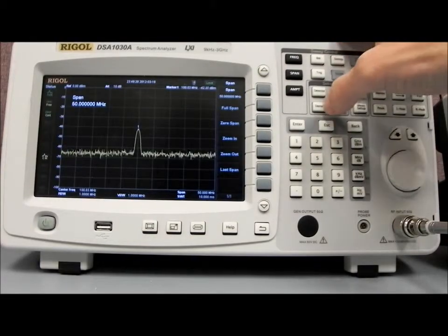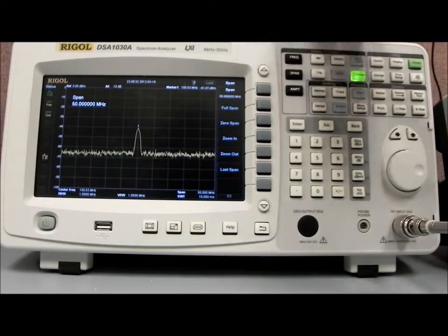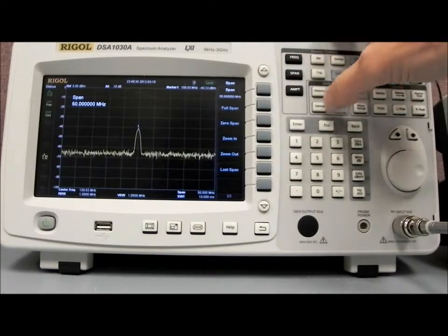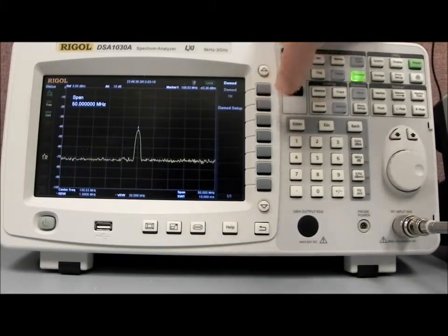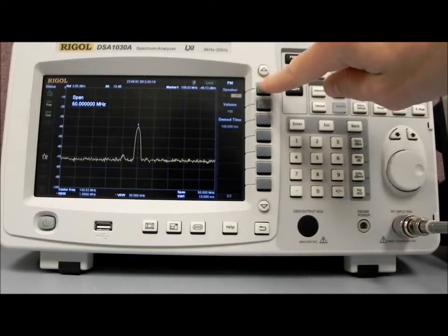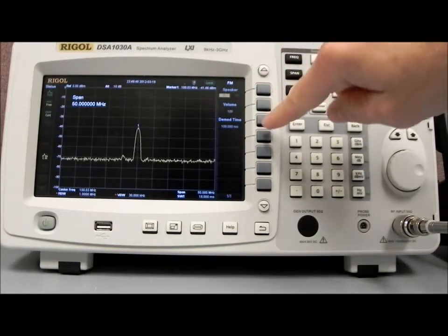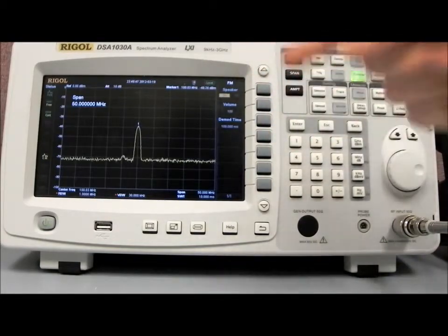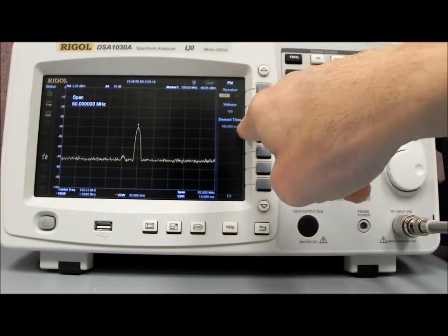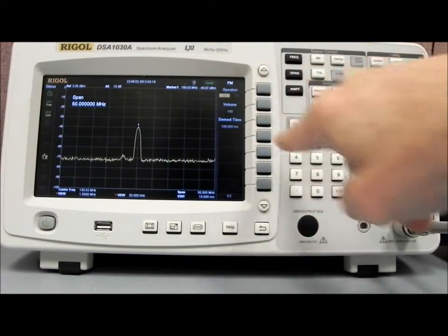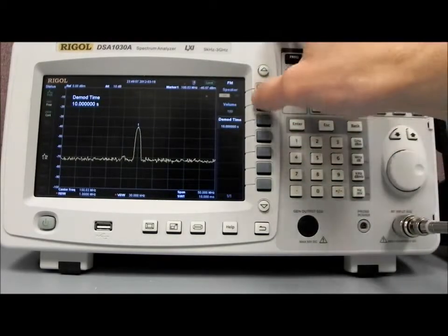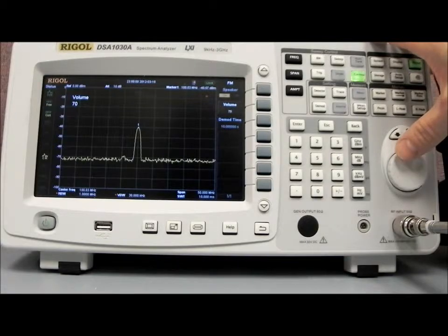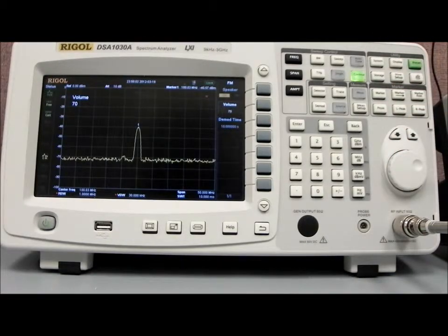And now what we can do is demodulate that input. As a standard feature with the DSA, we can press demod, turn the demod on to FM. Then we want to set it up, we can turn the speaker on. And you can hear it's going very, very rapidly. It's demodulating in 10 or 100 milliseconds. If we put that up to a larger value, let's say 10 seconds. And you can hear Bob Dylan in the background.